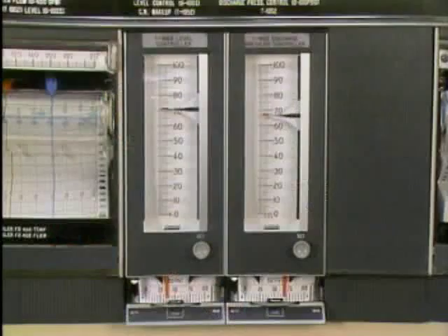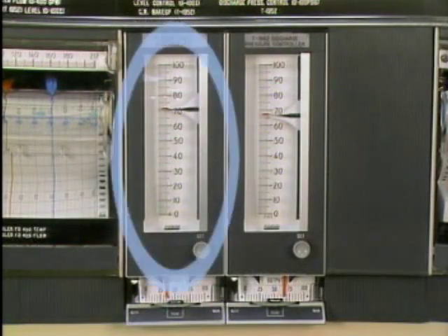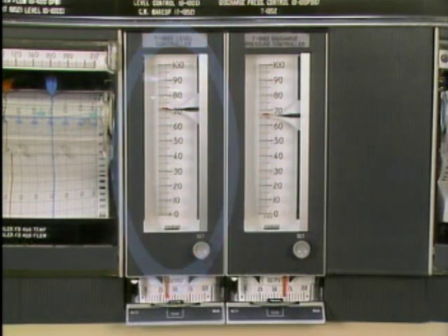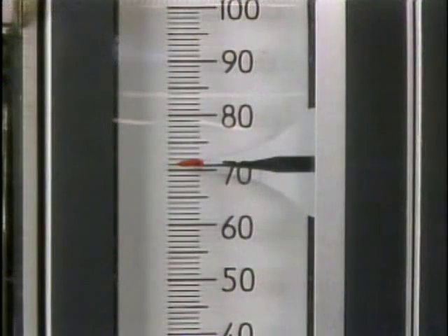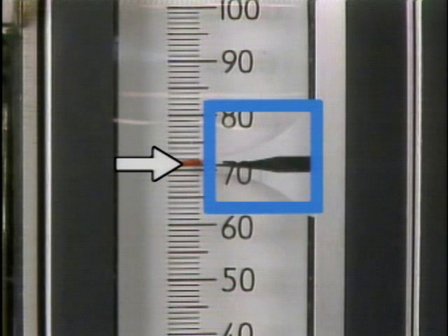After the controller output is set, it will remain constant. This keeps the final control element in the same position until the setting is changed by the operator or until the controller is set to automatic operation. For example, this controller can be switched to manual operation at any time. However, for a smooth transfer back to auto from manual, the value of the process variable and the value of set point should be the same.